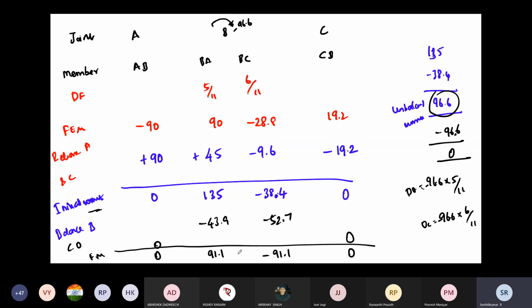So now it's all right. At joint B, if you are equating to 0, the summation of moment at joint B should be equal to 0. So that is solved. This is your final answer. So instead of solving equations or memorizing the formula, first you have to release the pin supports and arrive at the initial moments. These are the perfect moments for the given beam.